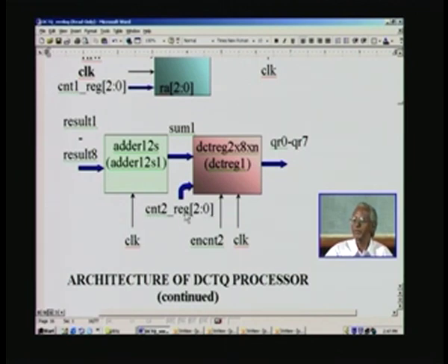As I mentioned before, it is all based on counters, and a second counter is invoked here, and it is a 3-bit counter, whereas the first is a 5-bit counter, or 6-bit, I think 6-bit counter, right, of which we have used only the LSB portion, and let us see where we use the MSB. And here this is nothing other than the address for the register that we want. So if it is the very first P00, this address will have to be 0, for P01 it will have to be 1, and automatically all this controller, I mean counter etc.